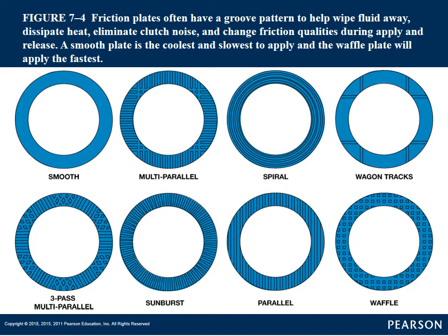Here are some different groove patterns you might find in clutch packs. I wouldn't say this is exhaustive by any means, but the manufacturers come up with a design and say, we feel that this is the best design to fit how we're applying this clutch pack, to best distribute the oil that is running through this clutch pack for the best application possible. That's essentially what it is.